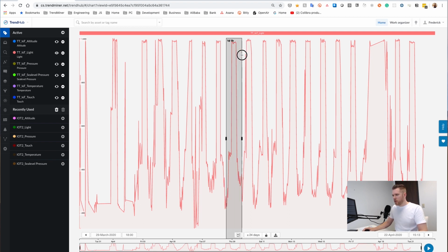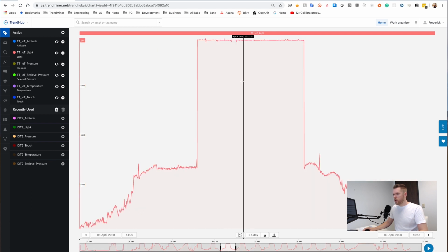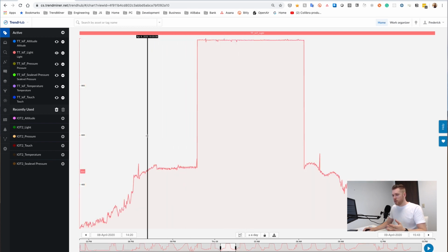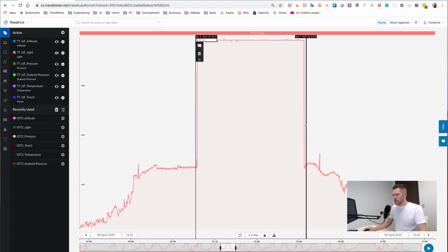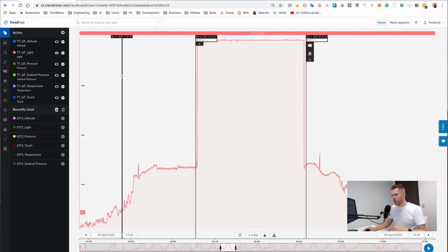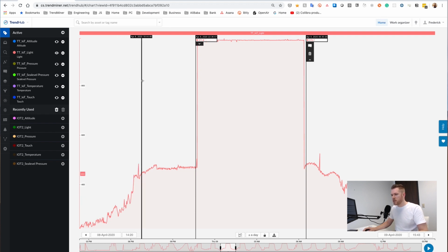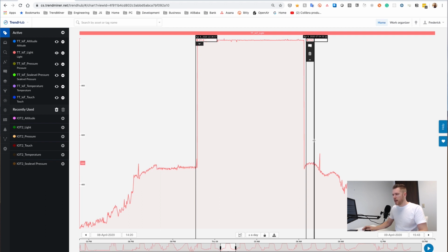Let me zoom into one particular day just to say a couple of things about this reading. And the first and most important thing to notice is that this is an inverse sensor. As you can see with the 2 data cursors around 10:30 p.m. to 6:30 a.m., the light reading is actually high. So high light readings means it's night, all the lights are turned off, there's no sunshine outside. And throughout the day, as we turn on lights, as the sun comes and shines on our patio and on our windows, you'll notice that the light sensor will go down. So it is an inverse sensor.